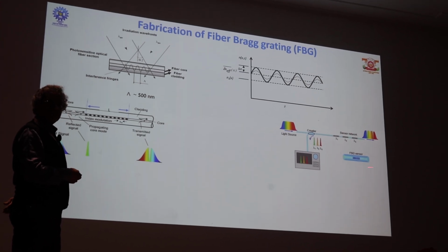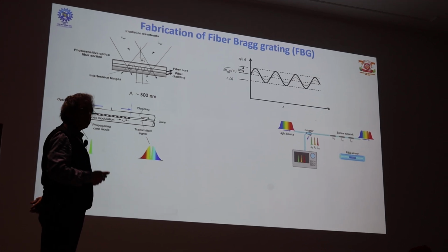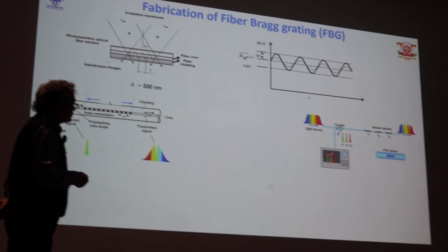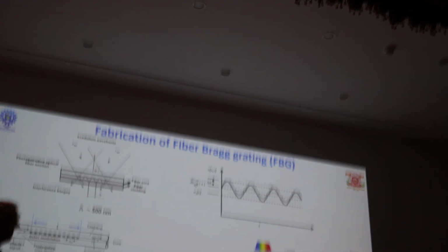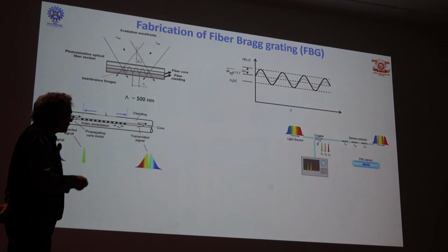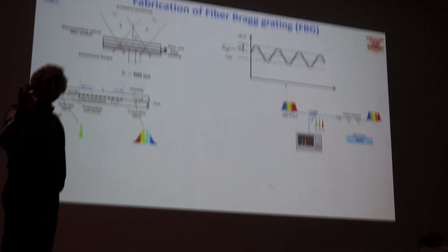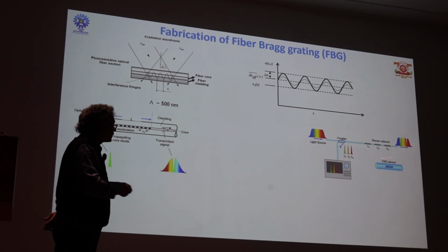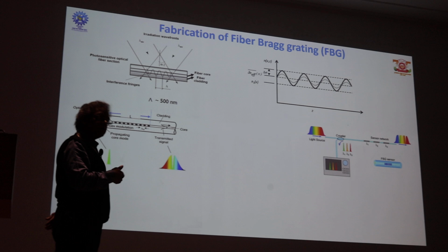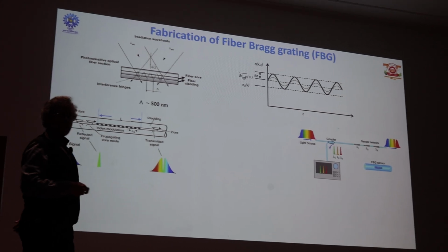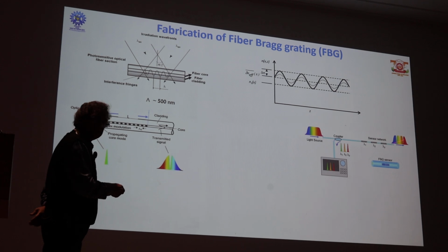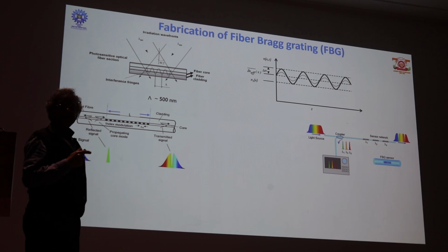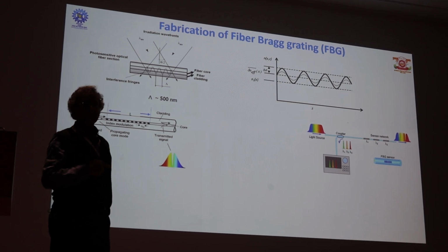One very important thing is why optical fiber Bragg gratings and these devices are coming in a big way. When you are impinging light in this link and detecting, these particular devices may be 2 kilometers away from your control room, and there will be almost no losses, because we are using a standard communication fiber which is transmitting the light. Only because you have inscribed a certain grating structure, you are getting that certain reflected wavelength back to your system. Now the question is, how will this be used as a sensor?